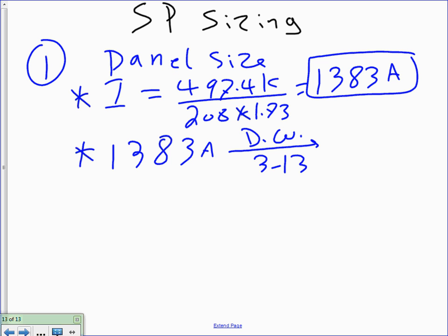We're sizing the panel, not the overcurrent protection device, the actual panel. 3-13. I want to remind you guys, go under switchboards or switchgear, 3-phase, not single phase. Okay, my options are 400, 600, 800, 1200. Can I do 1200? 1600. This is where, Joe, your judgment as an engineer comes in. Now, my options are 1200 or 600, actual physical big box.